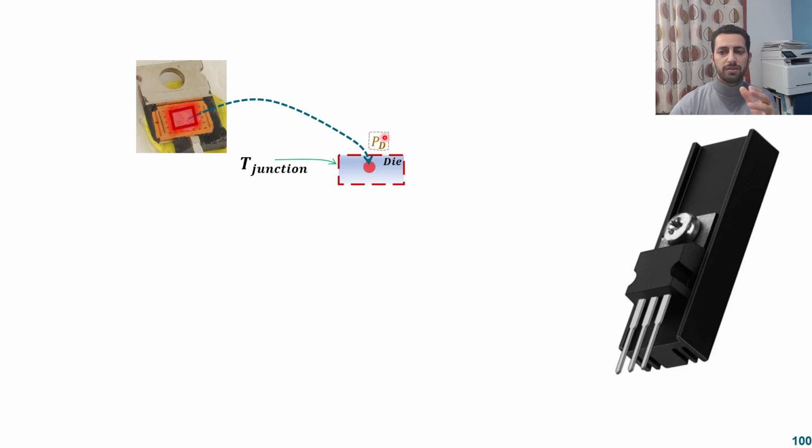So that's why we have here the temperature of the junction, and that die is sitting on the case, and while developing higher and higher current, and higher and higher temperature, the case will also develop a temperature, but less than the junction. Now, if the junction is 100 degrees Celsius, the case will be less than 100 degrees Celsius.